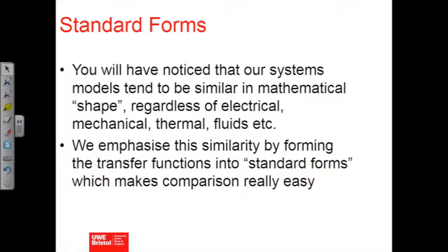The more you look at these systems, thermal systems, fluid systems, electrical things, mechanical things, when you simplify them down to a transfer function form, they all tend to take the same shape. They're mathematically very, very similar. Okay. And we're going to push that idea by further manipulating these into what are called standard forms.